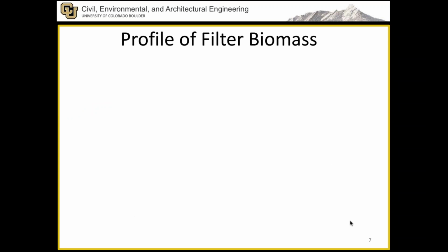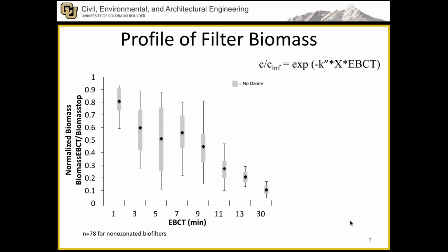In order to adequately model biofilter removal, we need to know the biomass concentration within the filter. And with this equation, that's represented by X. So we went to the literature and we found 78 studies for non-ozonated biofilters, and we plotted normalized biomass at specific empty bed contact times to biomass at the top.